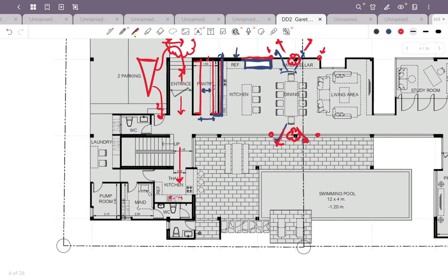And then about the zoning, this stair goes up to the bedroom, which means a privacy zone, right? But because it's too close to the door here, when you leave the door open and the owner is sitting here relaxing, watching TV, you will never see somebody sneaking up and hiding on the second floor. Because here is a public zone, but you put the stair that should be for the private zone in the public zone, and also in a hidden area too.